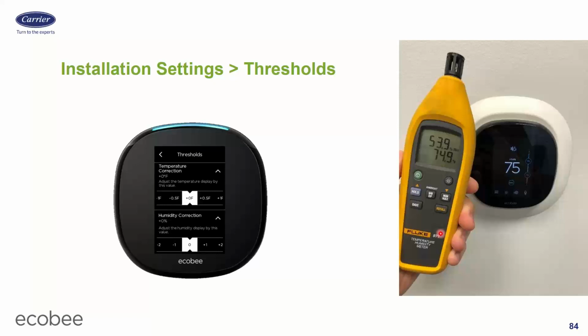Then down below all the staging related stuff, there's a couple more options on there. One of them is temperature correction. This is where you can calibrate the thermostat to match whatever you want to make it match. So in this picture here, I'm making it match my Fluke meter. Or actually, it already did match it, but I could have changed it if I needed to. So these sensors are pretty good. They're pretty accurate.